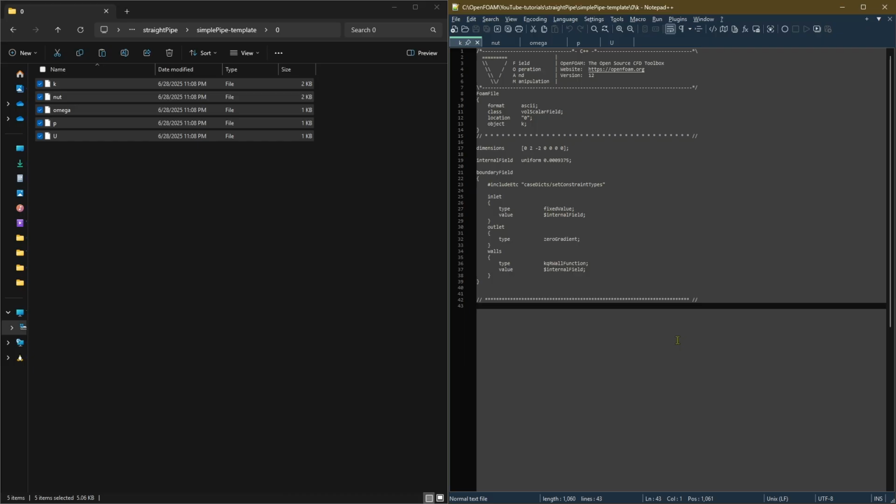What this function is going to do is set a zero gradient value for turbulent kinetic energy, where the idea is, for the physical assumption in the near wall region, we want the production of turbulence and its dissipation in local equilibrium, so to speak. In a typical simulation, you just want one wall function in isolation.